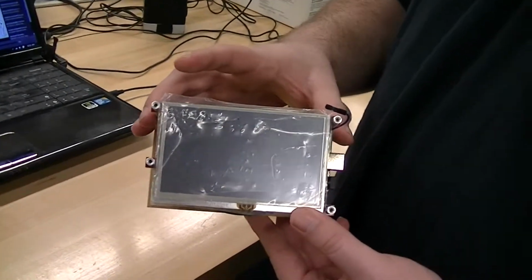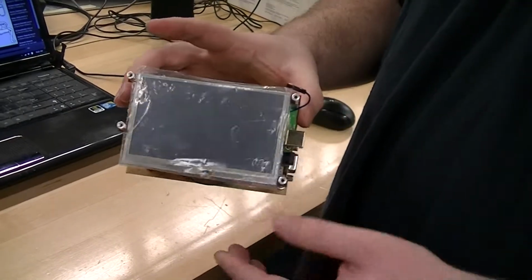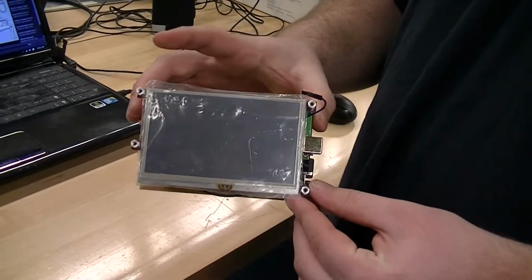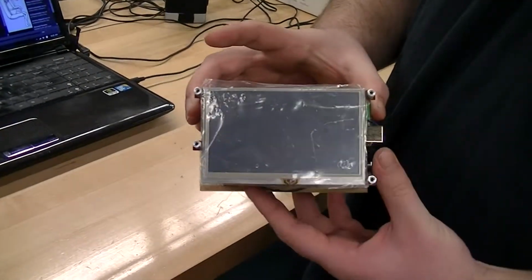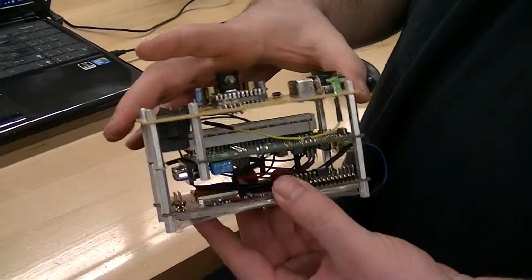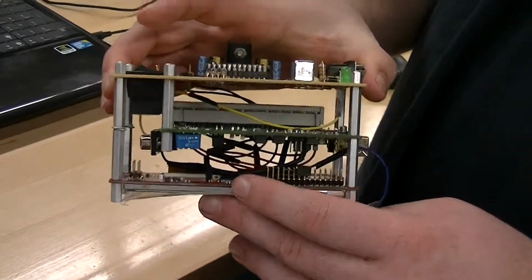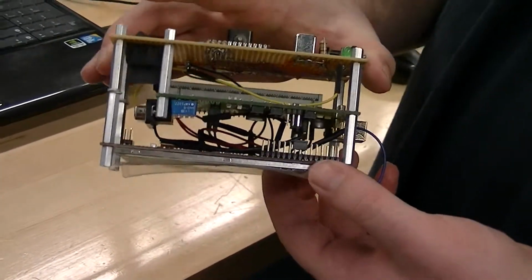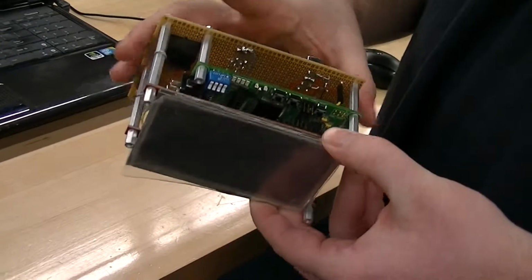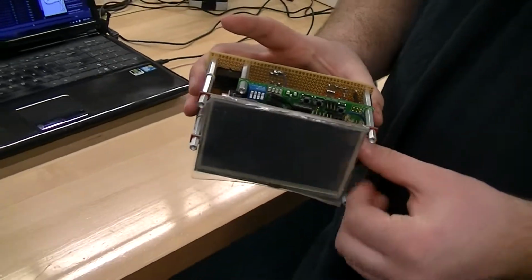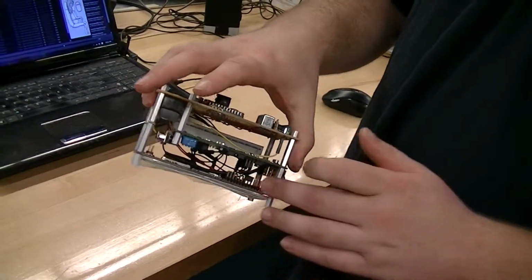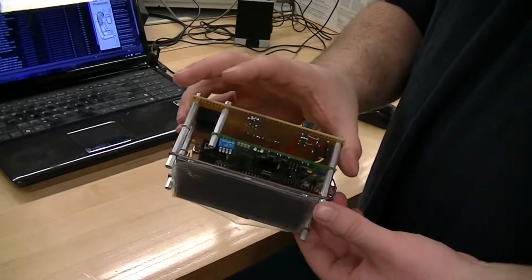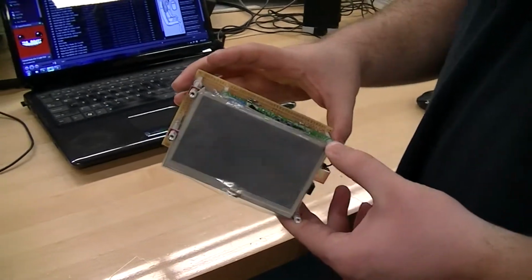Right. Now, what manufacturer is the display from? The touchscreen is from a company called 4D Systems. Okay. They're an Australian company. It's a resistive touchscreen. It has its own 16-bit microprocessor in here. The programming language is a mixture of C, BASIC, and I believe Pascal. They call it 4DGL, and it essentially is to control the screen, and has a couple of outputs like serial, CAN, and stuff like that. Okay, awesome.